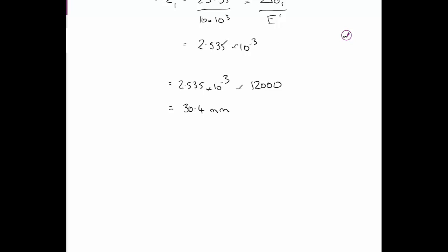So obviously there's more settlement. The drained condition implies that all the excess pore pressure is drained away. So we call that rho T for total settlement. We know the rho I from before, the initial settlement, was 15.6.